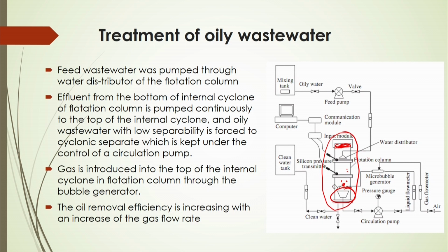You can calculate it based on the initial content of the oil and the final content in the solution. This process is given in this diagram, and in this diagram you can study how the oil content can be removed efficiently by this sparging process of the bubbles.